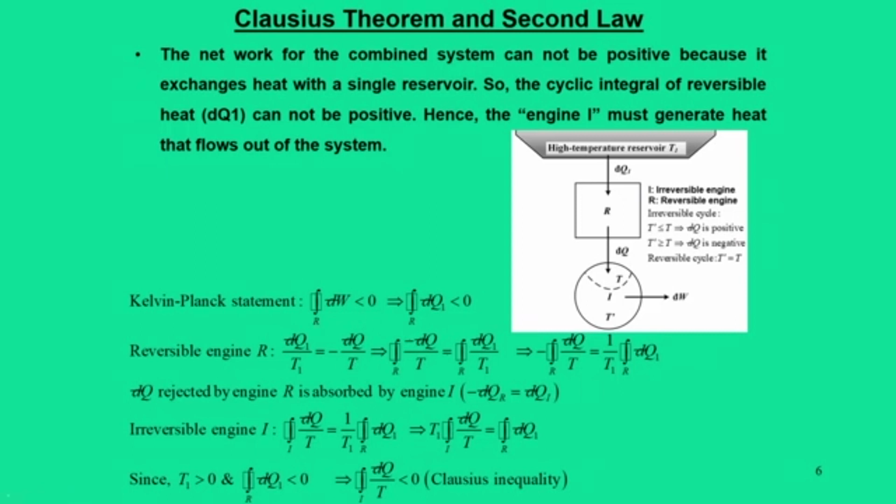This integral of ds is evaluated for the cycle. It goes in this way and in this path, two paths. The entropy for this irreversible path and the entropy for the reversible path. So this is from i to f, the integral of ds, plus from f to i the integral for the reversible path. Combining this together, and with respect to this equation, we replace this dq by T. So it's the cyclic integral, and this irreversible path is always greater, and on subtraction,